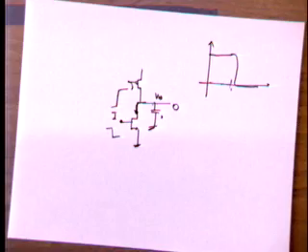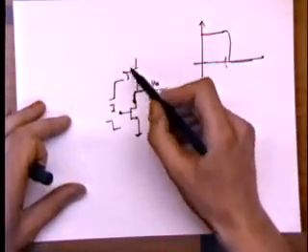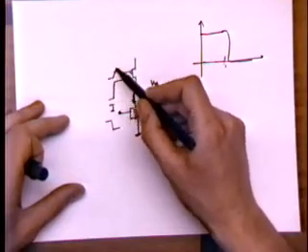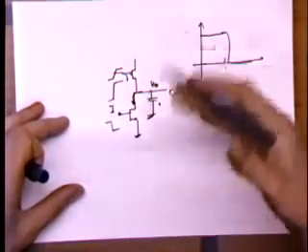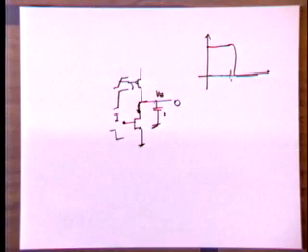You might also say, because I have lower capacitance, I have lower power, but that's not really true, because you are adding all these precharged devices, and these are commutating every clock cycle. So it turns out that dynamic is good for speed, but it's not good for power. For power, dynamic is usually worse.